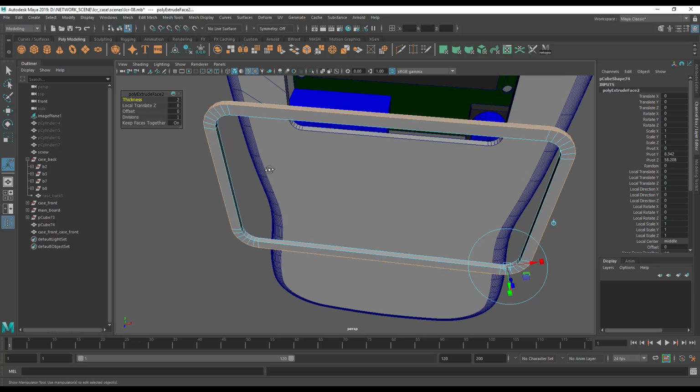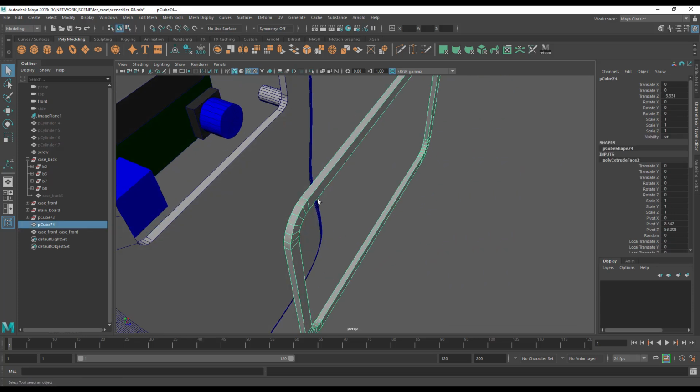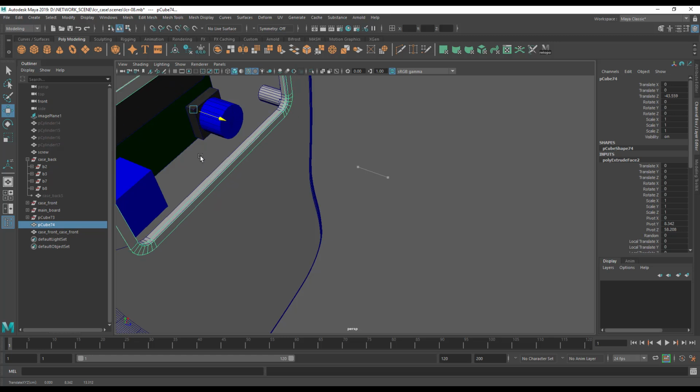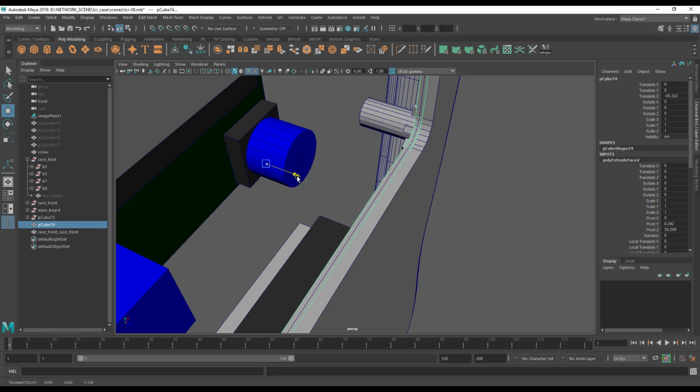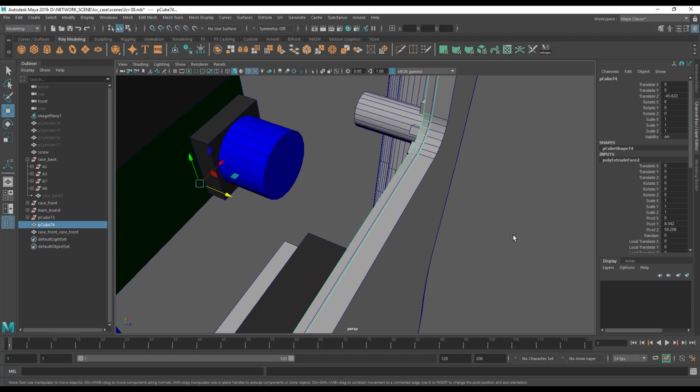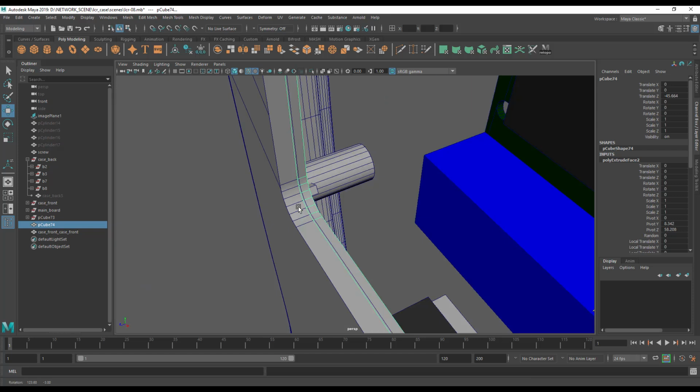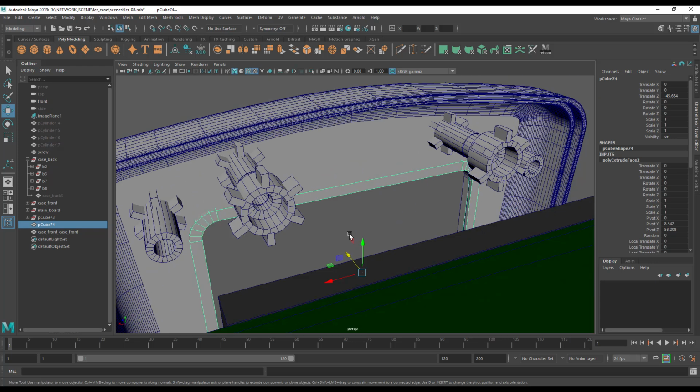There we go. Now I can shove this thing inside the case with W here, and if you wanted to make it exactly 1mm on the inside, you could extrude it to a 1.1 and create a 0.1 overlap here, but I just want to make sure that's overlapped, and that's going to be accurate enough for me.